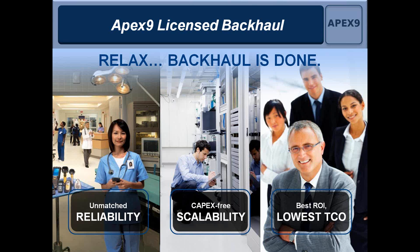Now, since you brought up rural, if you remember, the 4th bullet point on the slideshow talked about this rural waiver request. What that deals with is, if you remember from point 3, the efficiency standard that's required under Part 101 so people don't waste spectrum. In certain rural areas, maybe you're trying to stretch that link 60 miles, but it's not going to work with the appropriate 4 nines or 5 nines of reliability at 256 QAM, but you think you could make it work at QPSK instead.